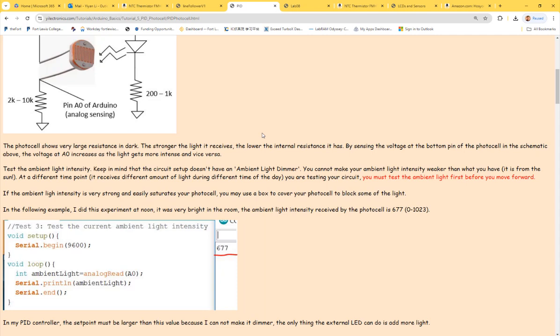Okay. So why does it make sense to control a motor though? So for example, I have a 2-wheel robot car. It won't be able to stand on the ground by itself because it's only 2 wheels. Okay? And I have an accelerometer on the top, which is able to sense the angle of the car. So whenever it's tilting forward, it's able to sense the angle and try to pull it back. How to pull it back? Roll the motor forward. Okay?